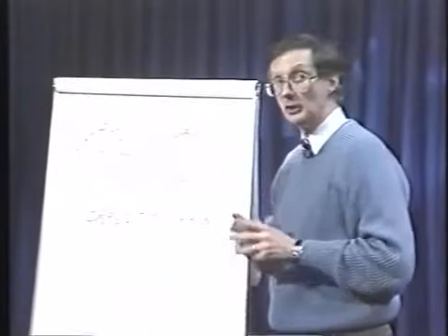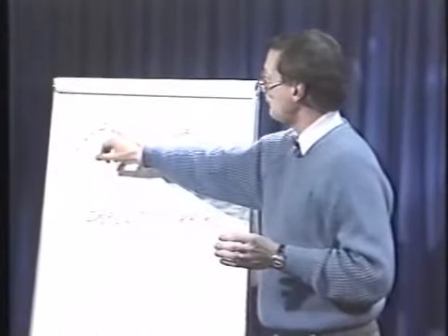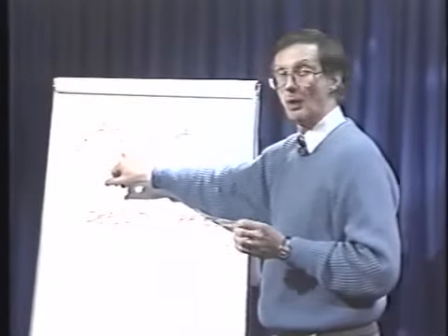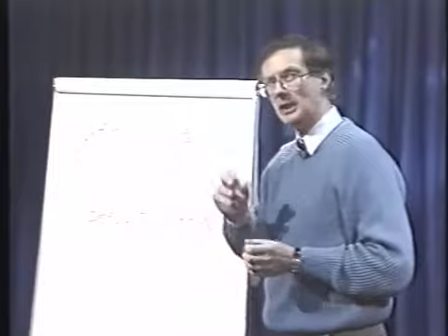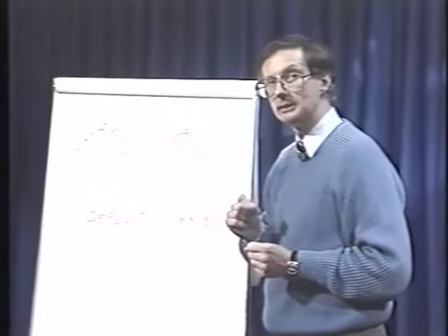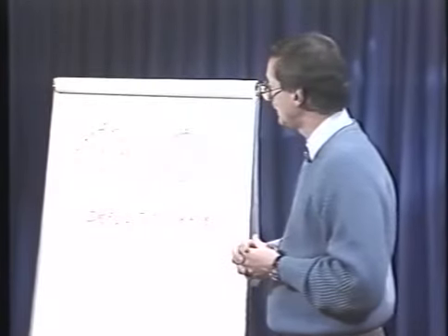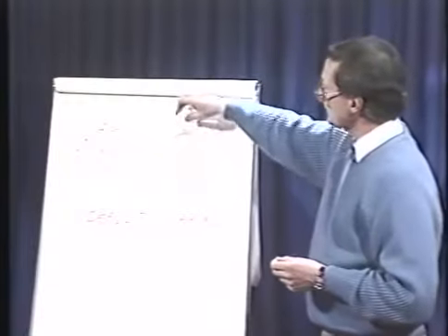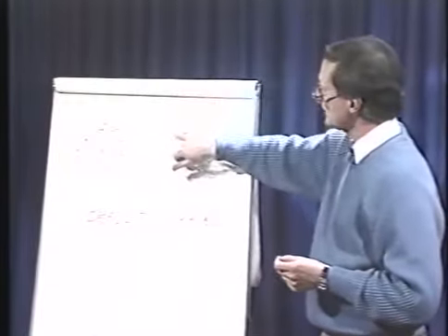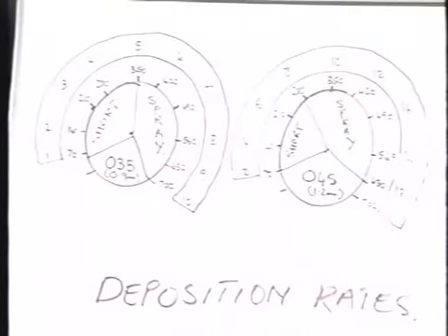As a matter of fact, you may wish to remember that every time you turn the wire feeder one increment with an 035 electrode, you are going up about 1 pound per hour. Now let's have a look at the 045 wire. The spray range again, we can see the difference now. For each incremental turn on the wire feeder, it's 2 pounds: 8, 10, 12.